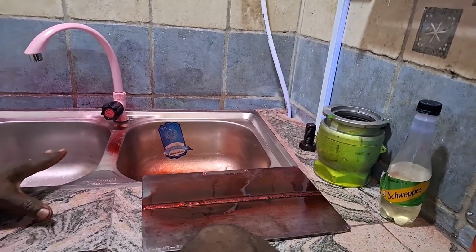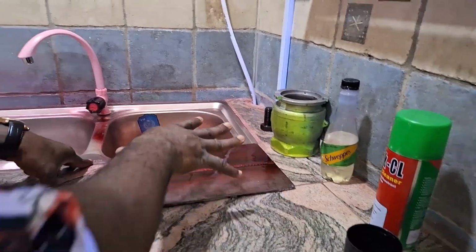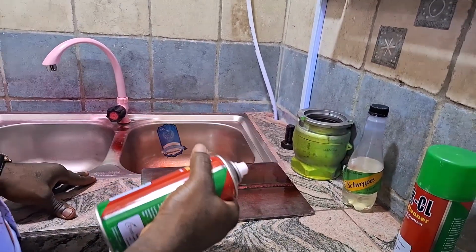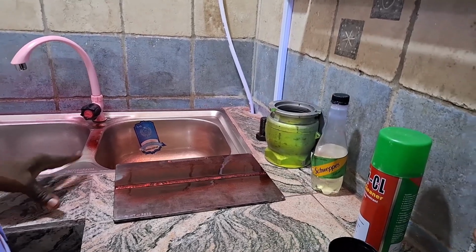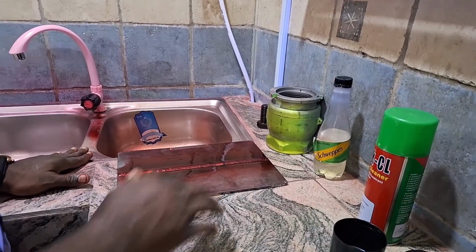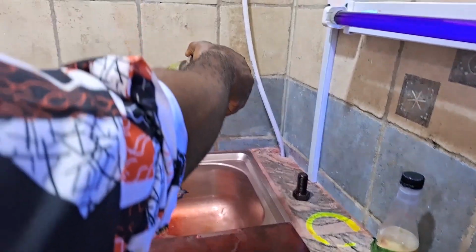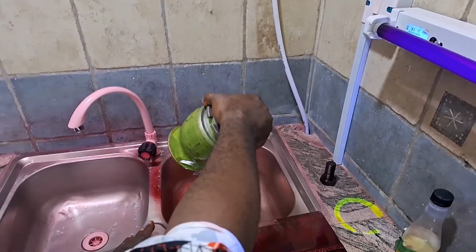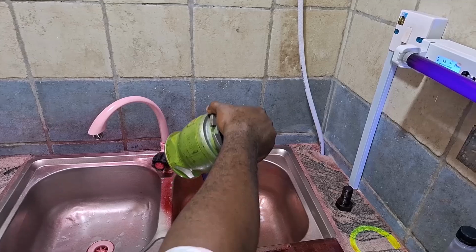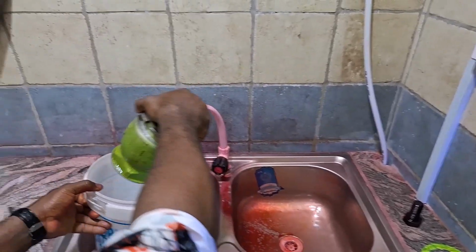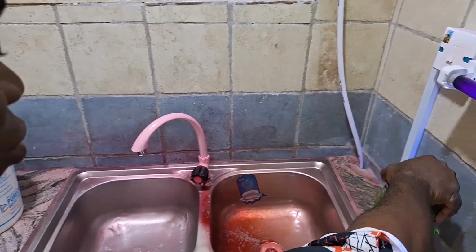For the application of a penetrant, for these ones I added penetrant, I did the spray method. There are a whole lot of methods of applying penetrant. For an item like this that I applied this type B to, we can use dipping, whereby we dip it into, let's say this is the penetrant in the pool, we dip it inside and leave it out to drain.